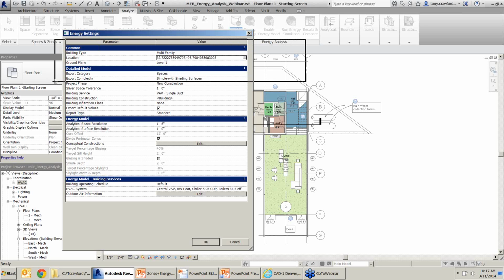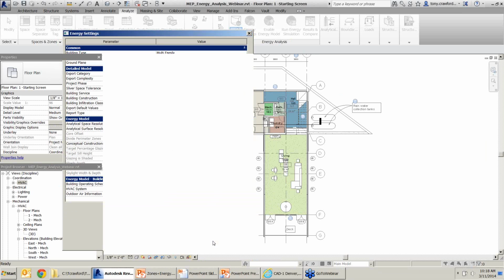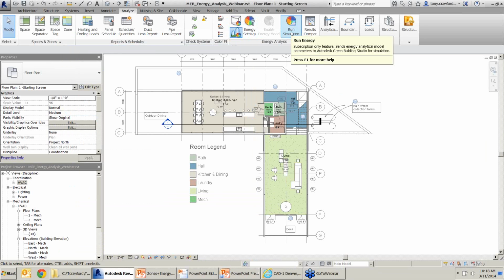So a couple of things that you want to do for this whole building conceptual: you want to give it a building type and a location. And that's the minimum that you would want to use. The more, especially in the bottom half of this, the more that you do add will make it more accurate. But let's just hit OK on this. But in your early phases, you may not know what that is, so you keep it fairly general, and then as you move through the project, you tighten those things up. Exactly, and that's the 3 phases that I have on here.